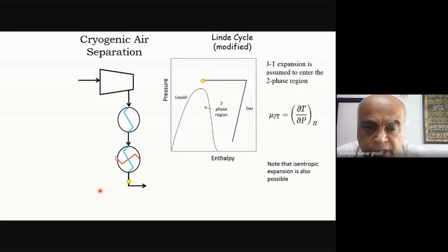You might first just use, let's say, chilled water or even ambient water and cool it down. But later on you'll find that there are certain waste streams which will come out from my Linde process, which will come out cold. And before I discharge them into the atmosphere or into my product, I will obviously utilize their low temperature to cool down my feed stream. So this is what cools it down further.